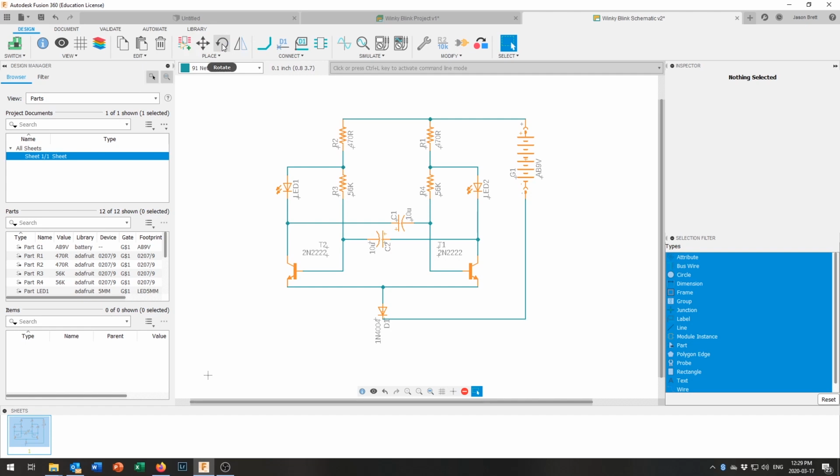And we can make that easier by coming up here and selecting the rotate button. And for C1, you have to get right over top of that little crosshair, and we can rotate that into a vertical position. And we can do the same for the 10U. We're going to come back and move that later on, but let's just go and find, whoops, I rotated that too many times. There we go. Make that 10U. Again, too much clicking on there.